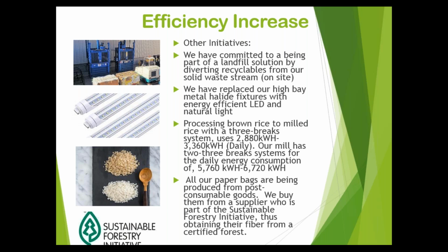Another thing that I'd like to mention that's not anything that we've done here at ACC, but that we're seeing as a trend throughout most of the westernized world, is that consuming healthy products becomes more and more the trend. There's a lot more consumption of brown rice, and what we're seeing there is that we're consuming a lot less energy when we mill rice to brown instead of to white. We use about half of the equipment, and because we don't need to run our whiteners at all, we just need to run our huskers, just take the husk off of the rice and then send it out as brown. So you can see there that milling rice to brown from white has about a 3,000 kilowatt hour daily savings.